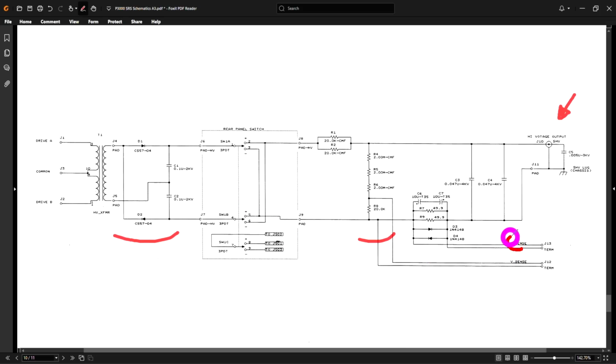Now there's one other thing they can use iSense for, and that is to detect trip, so that if it goes over 25 watts, this input basically stops. The inverter no longer applies signals to the transformer and the whole output gets disabled, and the user is then told that, okay, the circuit has tripped. It's a pretty nice safety feature, but both of these, iSense and vSense, have to be simultaneously used.